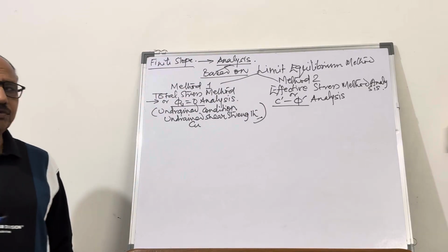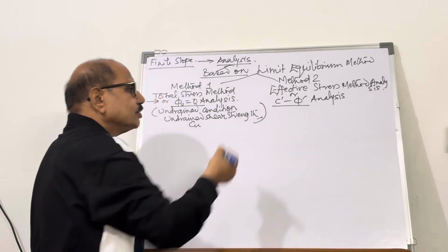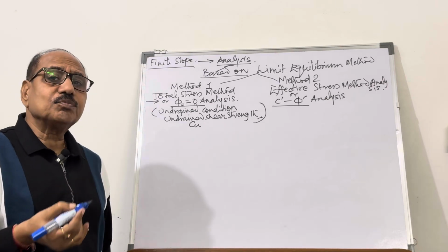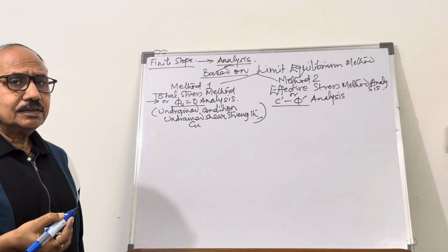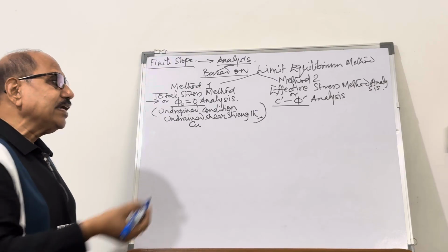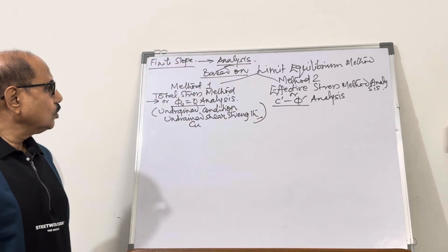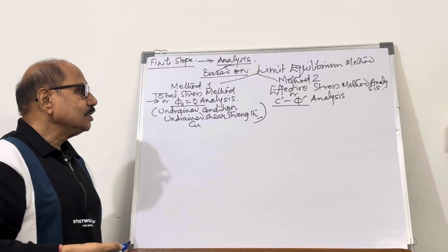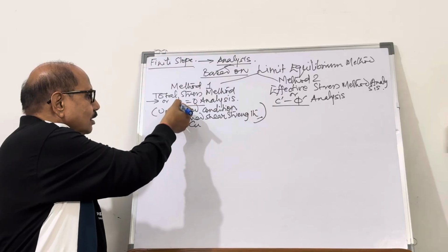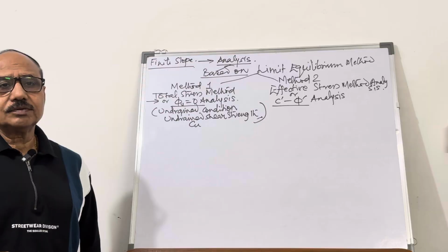So friends, you know about it. The determination of the shear strength after the excess pore water pressure has dissipated is mandatory, and that can be easily done. Whereas to simulate the undrained condition, the pore water pressure is going to be, it is a total stress analysis.